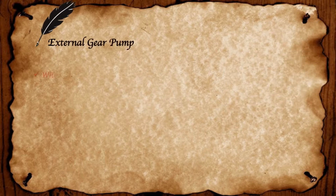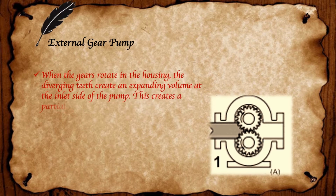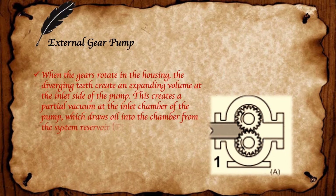External gear pump. When the gear rotates in the housing, the diverging teeth create an expanding volume at the inlet side of the pump. This creates a partial vacuum at the inlet chamber of the pump, which draws oil into the chamber from the system reservoir. Figure A.